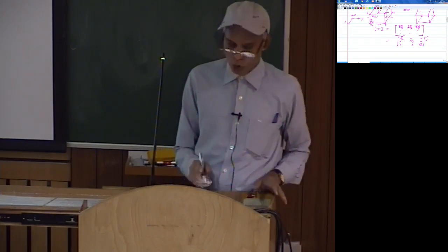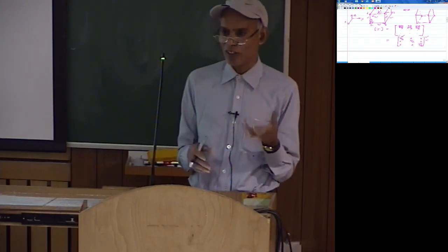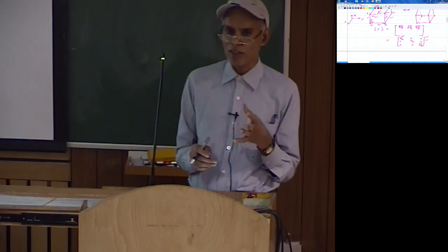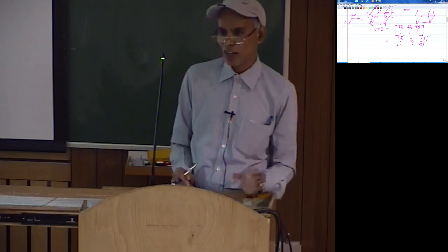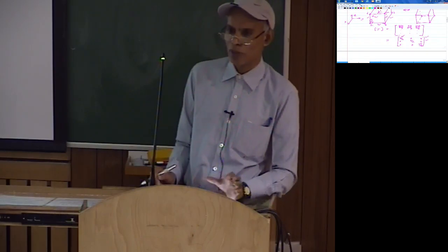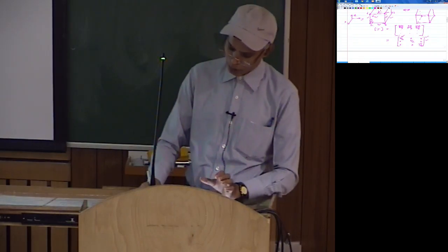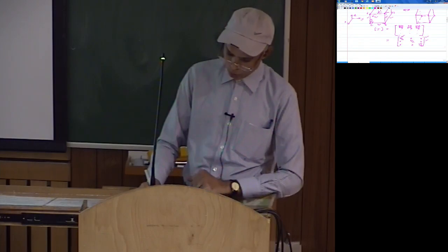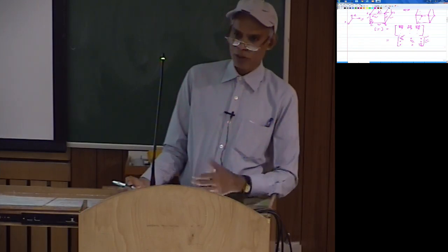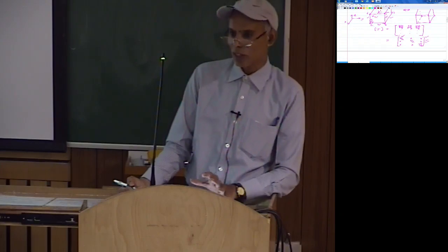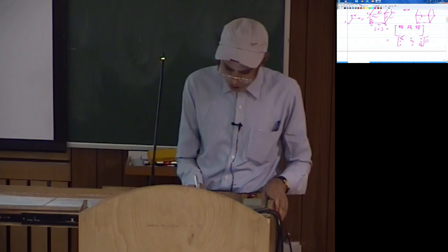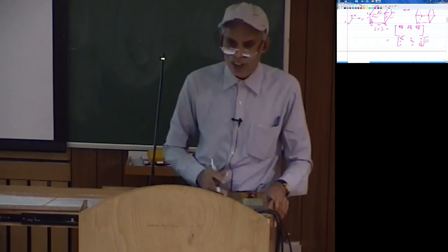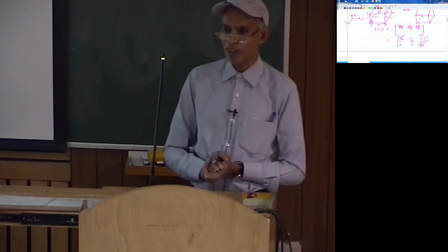In the physical coordinate space, when you discretize the structure, the ratios of the element edge lengths must be between 1 and 10. 1 is ideal, 10 is usually the maximum permitted. That will give you a properly conditioned Jacobian matrix, so that its inverse is properly evaluated. So that is one aspect. The second is when these angles are not 90 degrees, but different from 90 degrees.